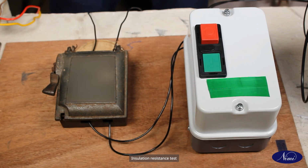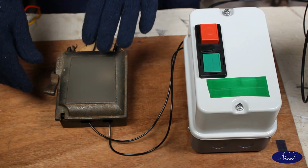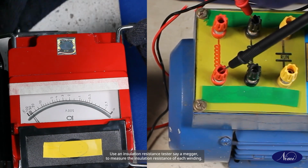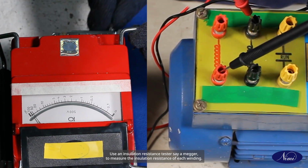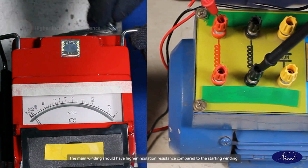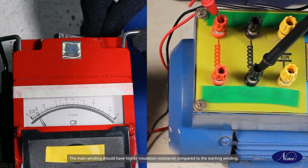Insulation resistance test. Ensure the motor is disconnected from the power supply. Use an insulation resistance tester, say a megger, to measure the insulation resistance of each winding. The main winding should have higher insulation resistance compared to the starting winding.